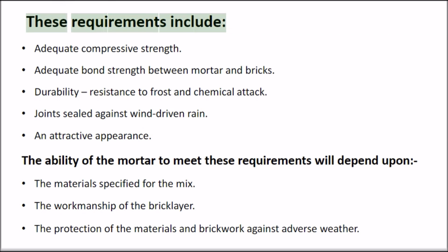These requirements include adequate compressive strength, adequate bond strength between mortar and bricks, durability, resistance to frost and chemical attack, joints sealed against wind-driven rain, and an attractive appearance.